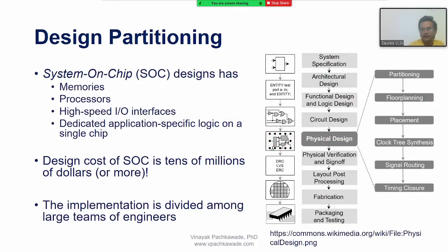So you can see here the blocks have been placed and there is wiring in between them. The tool will do it for you, but you have to understand, because you have to analyze it and perform some verification steps to check whether this routing and placement is correct, and that's the job of the PD engineer. Then there is clock tree synthesis.